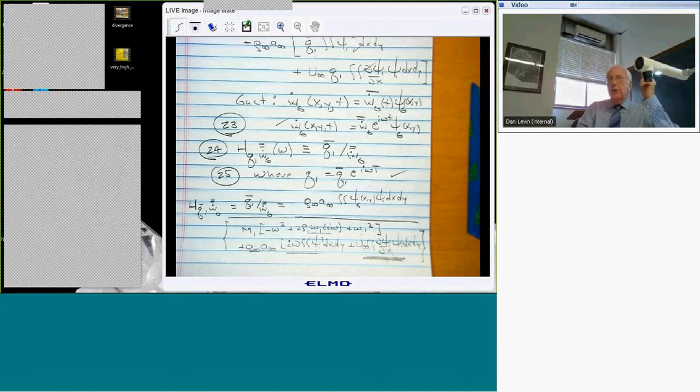So you will see in the literature a discussion of two-mode flutter, or more commonly it will be called bending-torsion flutter, because the classical two modes that people look at in an airplane wing are bending and twisting of a wing. And even for panels, which are a different story, plate-like structures, usually you can identify two critical modes.